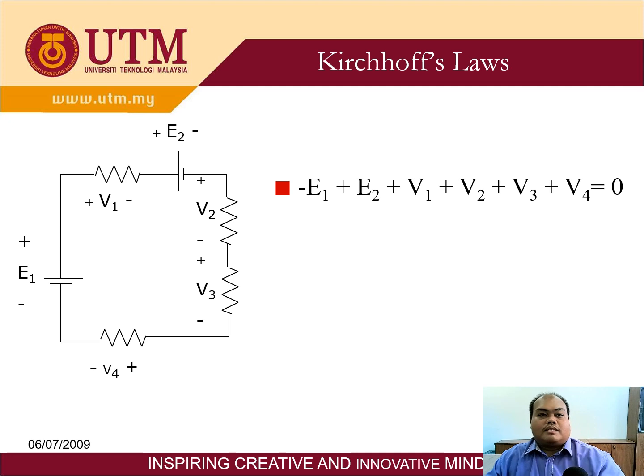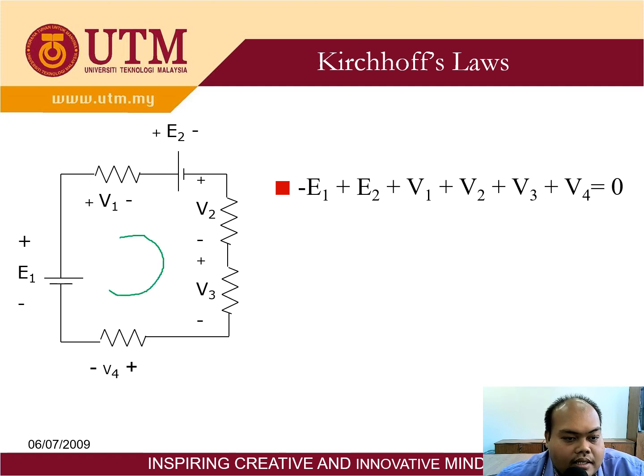Okay, how to do this? If you can see here, we create a loop and apply Kirchhoff voltage law. Remember I said when you create a loop, make sure that the current that meets the loop needs to be positive, positive and positive for passive elements.